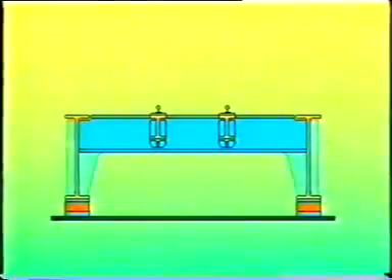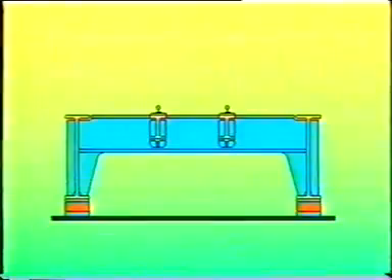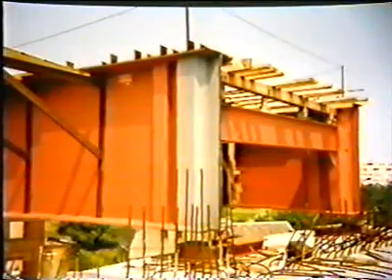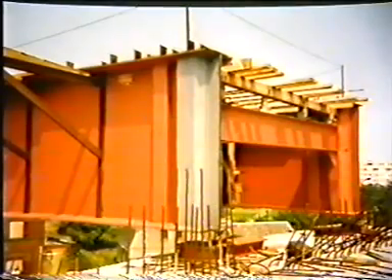By inserting brackets, horizontal forces can be transmitted to the supports, avoiding large deflections. They also distribute the reaction forces into the web. Instability is thus avoided.